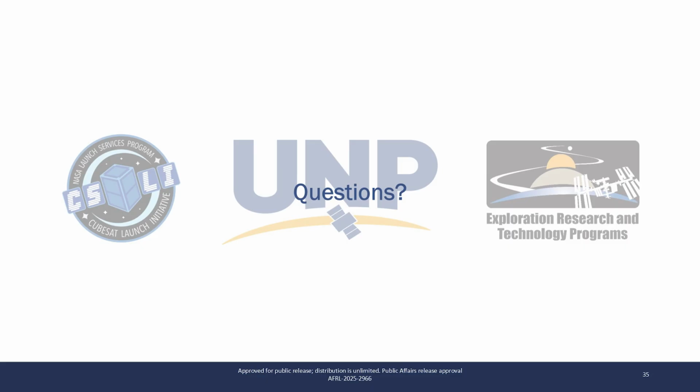Are there many CubeSats that actually exploit that disturbance torque, gravity gradient disturbance torque with gravity gradient booms? Not really, because we are still just such small form factors. No, it hasn't really come into effect. If you did deploy a boom, there are the mechanical challenges of said boom, as well as the storage of that, right? You may be using a third of your space just to have the storage of that boom, and then you deploy it, and now that volume is sort of unused for the rest of your mission. There's a few reasons why that trade usually doesn't seem to work out.